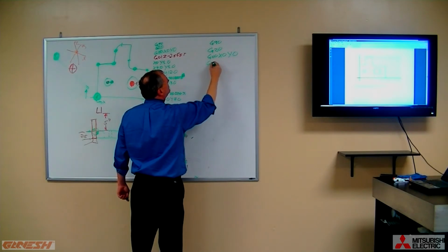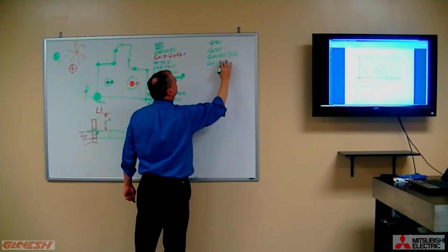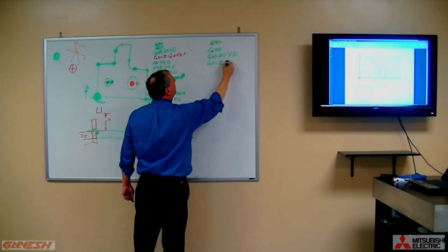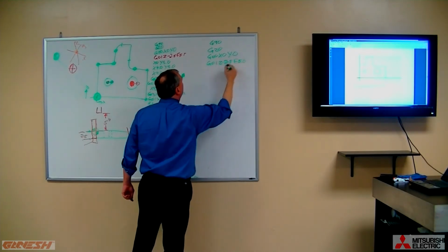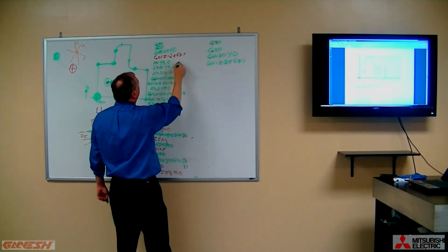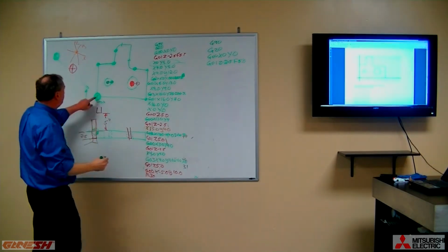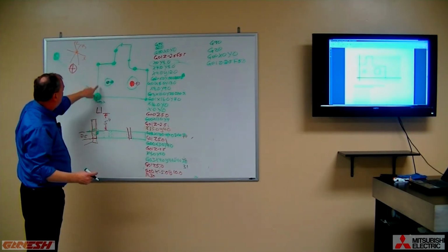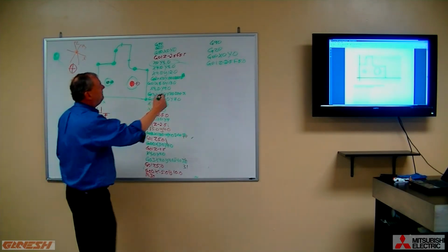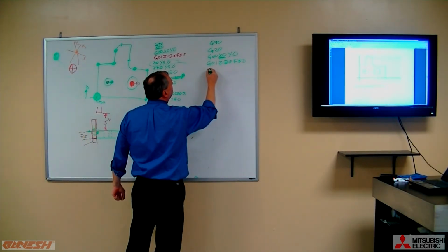And then we're going to do our G01 to Z minus 2.5, feed rate of 5.0. And now our next line is going to say X0, Y8.0. So I don't need to restate the X0 if it's the same as it was in the previous block. So X0 is there. So now all I need to do is say Y8.0.